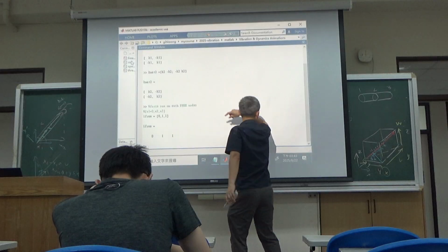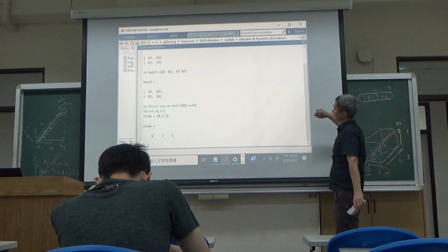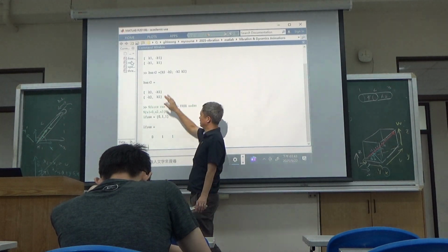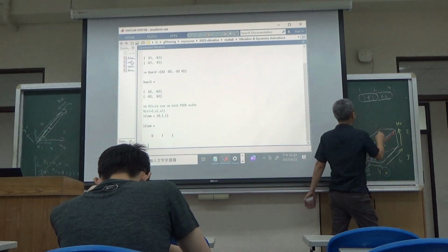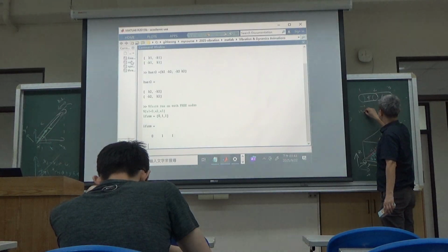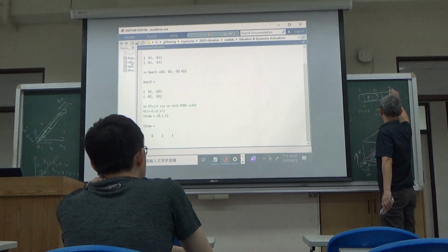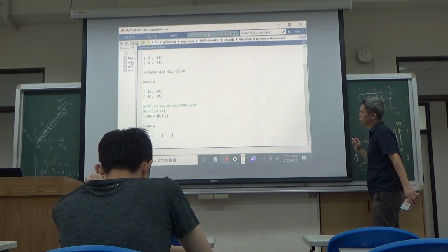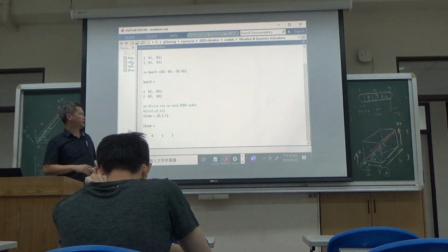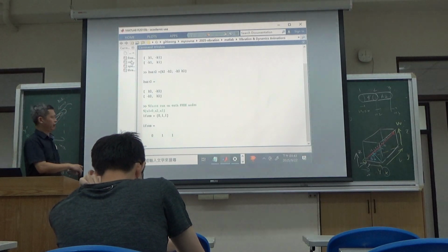If the first element is K1, the second element is K2. You have the stiffness matrix for the first element, the stiffness matrix for the second element, but you still have to define where the free degrees of freedom are. So you might have U1 fixed, you might have U2 free to move, and you might have U3 free to move under the loading. So what shall we define? We shall define 3 degrees of freedom.